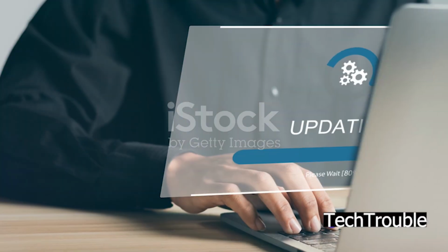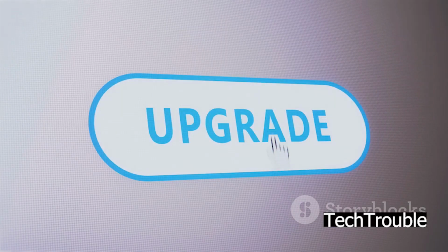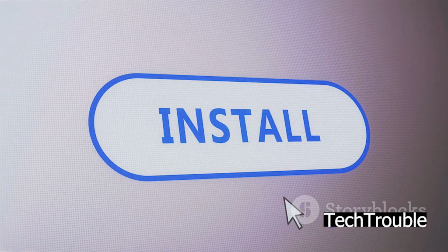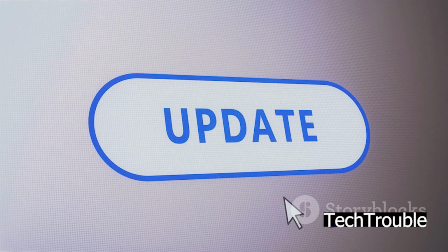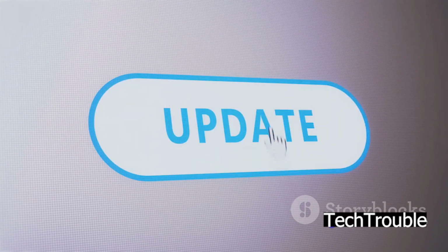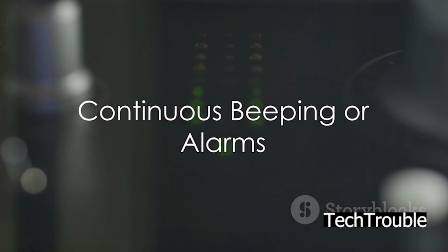If you're encountering errors with UPS software, ensure that the software is compatible with your operating system and UPS model. Keep the software updated to the latest version available from the manufacturer's website and verify the communication settings between the UPS and computer. Another issue you might face is continuous beeping or alarms.